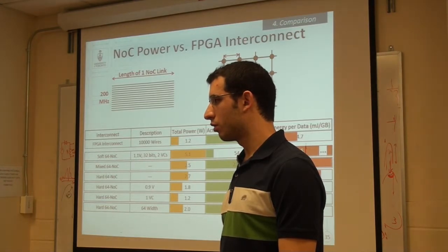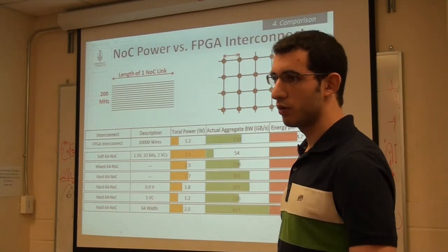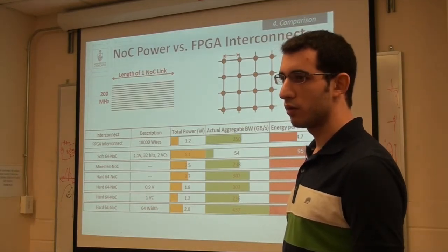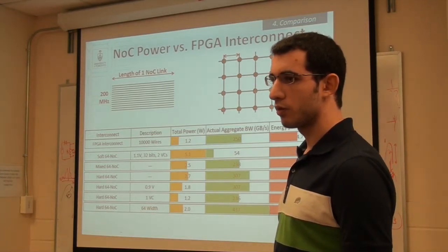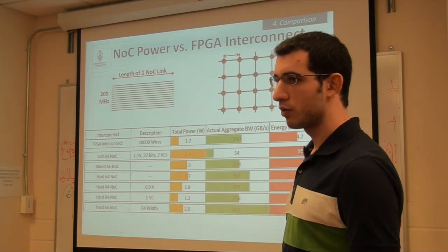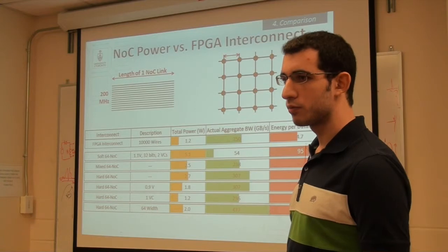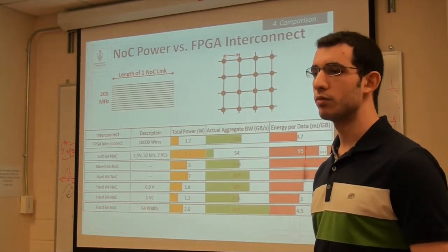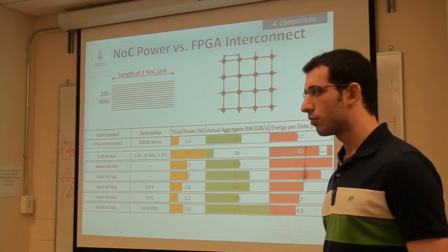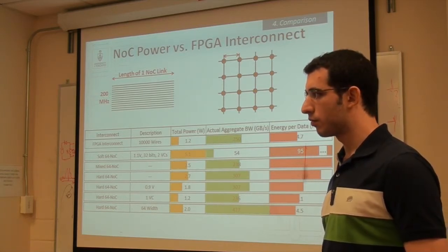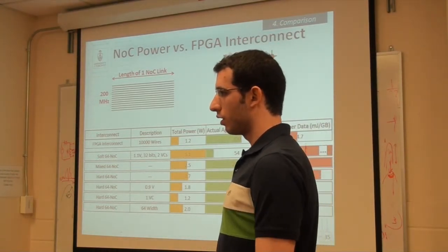And if you did the same average of near and far for QSys, it was very close to 10.5 nanoseconds. So that's between 2 distance configurations, close and far even? It was comparing the QSys close system to the NOC close system, and then the QSys far to the NOC far, and just averaging the numbers. Basically, both were quite close. But because QSys had to add more pipelining at a slower frequency. The NOC has 2 to 3 pipe stages because it speculates, right? So per router, but at a much higher frequency. In the end, it depends, though, for both systems where things end up being.